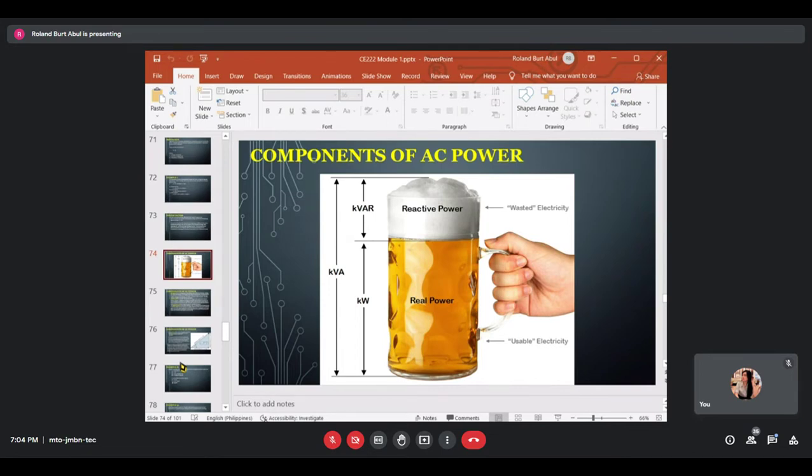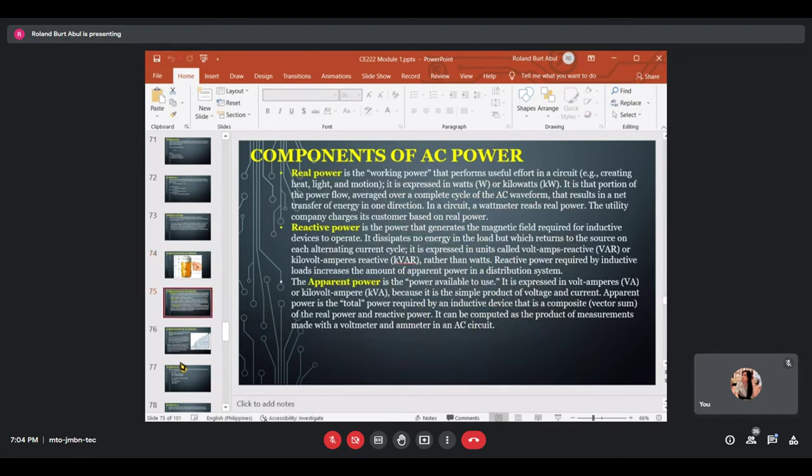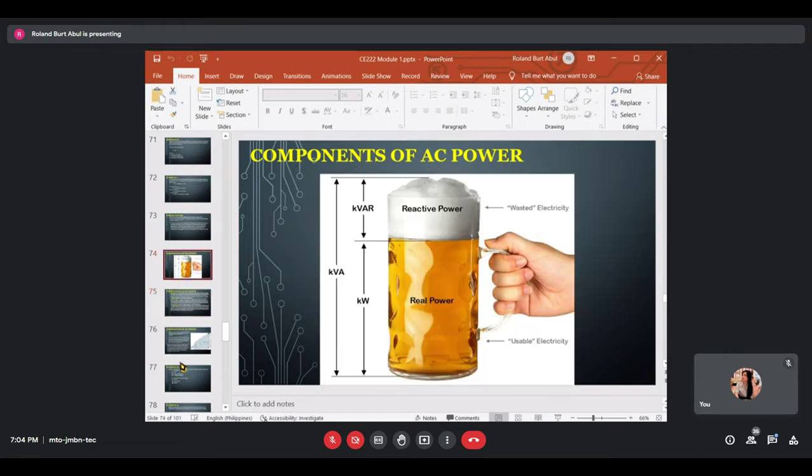DC and AC circuits behave differently with respect to power use. On a DC circuit, voltage and current are measured, and the product of measured voltage and measured amperage equals wattage. So P is equal to voltage times current, or P equals E times I. On most AC circuits, the computed volt-amperage is different from power consumed. That is, the product of the measured voltage and amperage does not equal wattage. This phenomenon is related to the inductive effects in circuits powering motors, transformers, and magnetic ballast as described earlier in the inductors section.